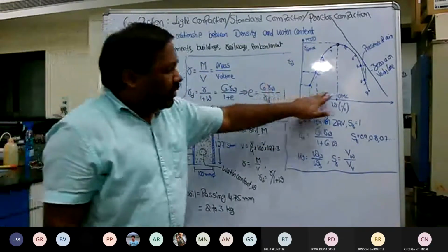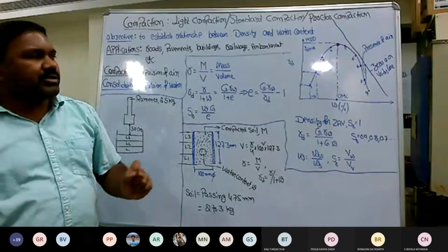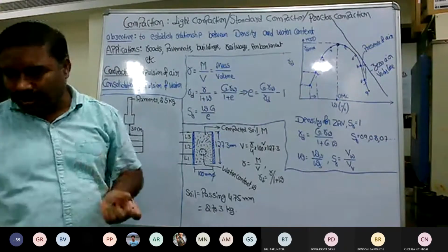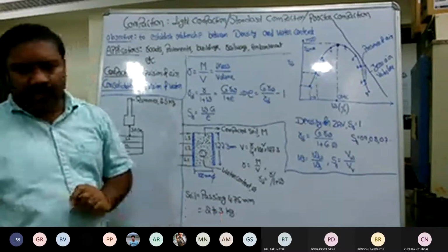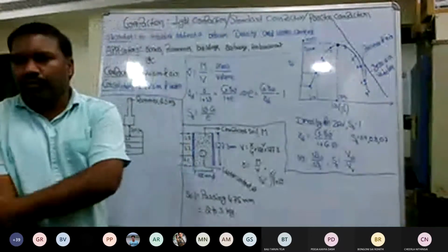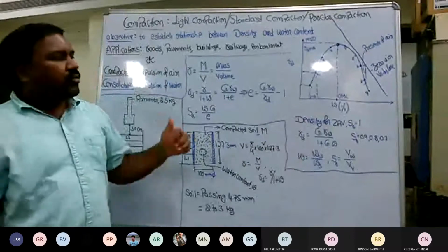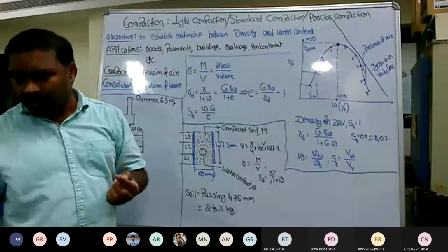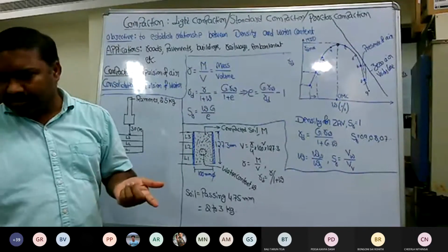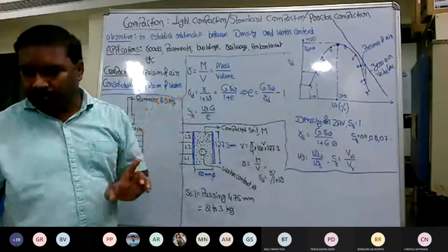But when you are adding the water, what you are fundamentally doing is taking the mass constant, maybe a soil mass of 2 to 3 kgs, but you are increasing the water content. So where does this increased water content go? Now, as you know from your fundamentals, if you take out any soil, we have soil solids and we have the volume of the voids. All this added water simply occupies the available volumes.